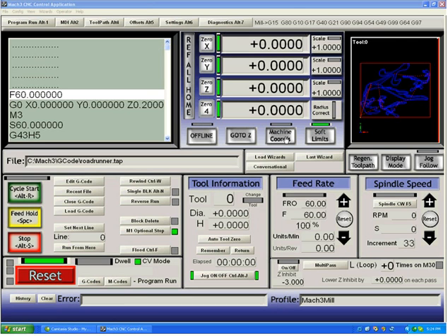The first is this button, machine coordinates. When the red LED is lit, you are showing what the machine thinks is the distance from the home switches. You'll notice mine says 0, which means my machine thinks it's sitting right beside the home switches. If I turn it off, I'm at the work offset.